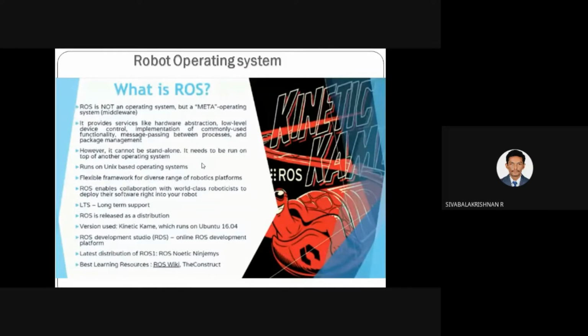If you want to make the pick and place, the first thing is you have to detect the object, and then inform the robot to pick the object. Initially there is a camera, which is one type of process, and it will detect the object. The camera detects the object and transforms the object location in terms of a transformation matrix.